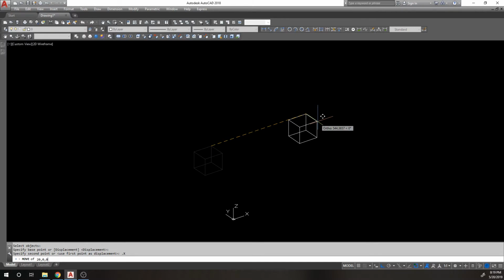And that's the equivalent of a line that is 20 units away from the x-axis and me snapping to the end of that line. Because my y and my z are 0, and my x is at 20. So that's the coordinate I want to line this thing up with. So I say enter, and I say @.